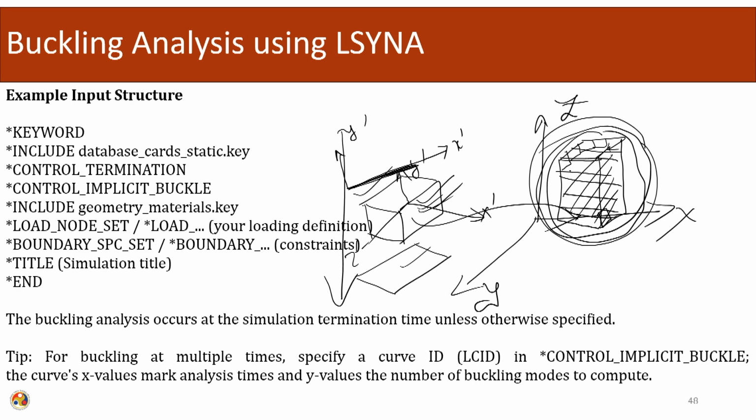Inside, what is going to happen is that each section will have its own matrix formulation, its own stiffness formulation. Depending upon the localized coordinate system, each will have a local stiffness, a k local. Let us say it is a small bar.